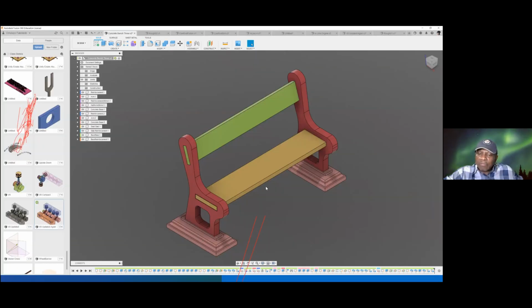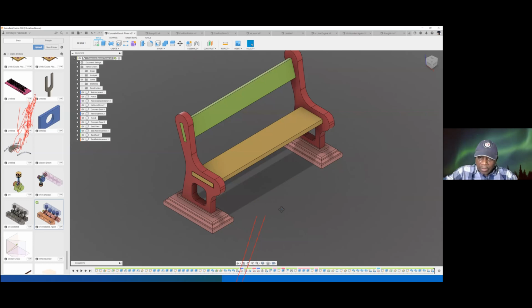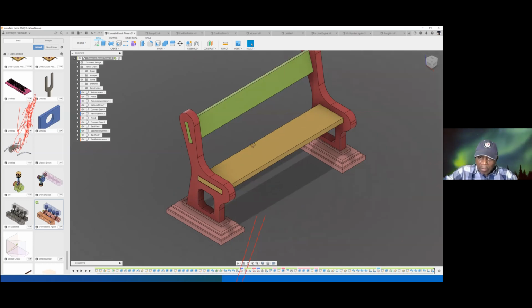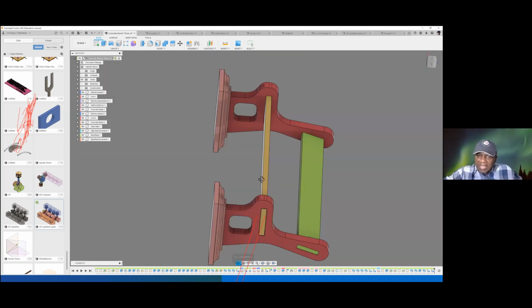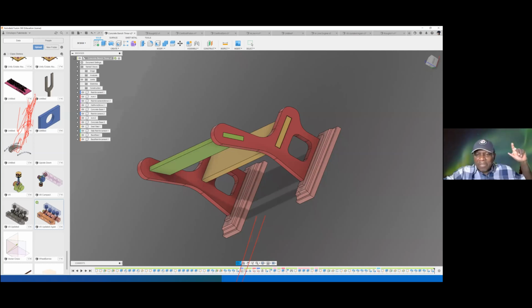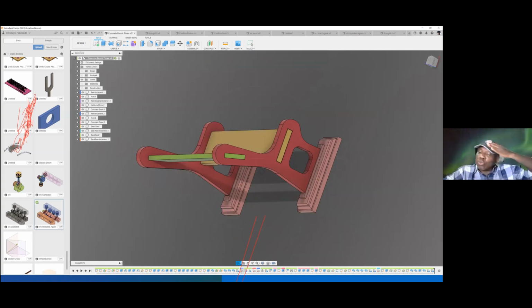So you can see, once I choose ground shadow, you can see this. And let me even do an orbit. Okay, let me do a free orbit. You see, the one thing about the shadow is that even though this thing is looking like this, it's still reminding you which way up is, because up is the opposite of where the shadow is set. So the shadow can be useful for you, because you have a complicated drawing, you may not remember where you set to be your up or down.